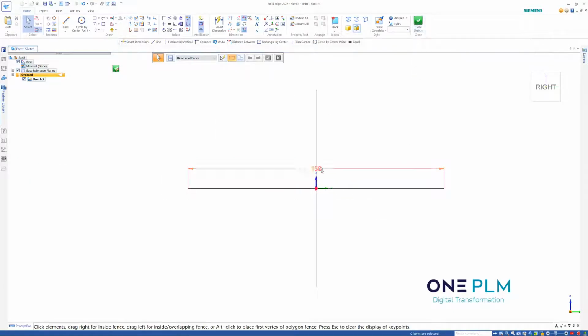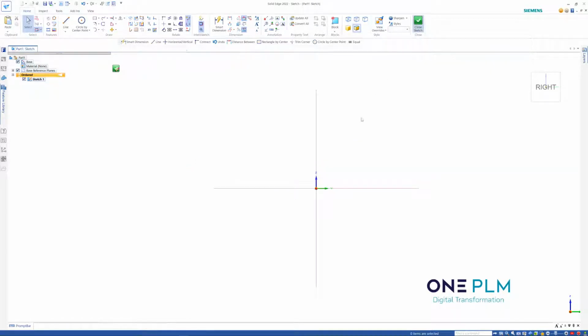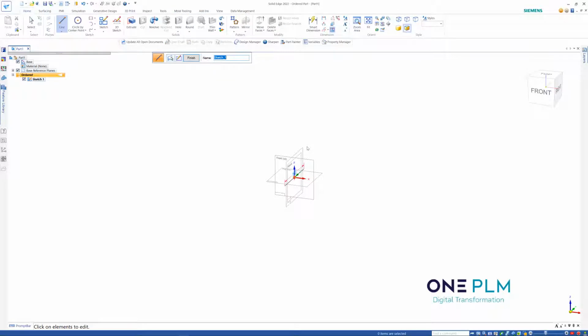Okay, and then we need to make sure that is L. So if we double click on that, the formula is going to be L, and that is then going to change the color. That is being driven by that size and that length that we've got. It could obviously be times 10 minus a certain value if you want to decide the centers, but I'm just keeping the center section roughly 10 times whatever the size we've got. So that is going to be length sketch. We don't really need to change that one.